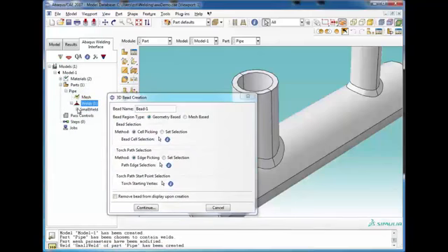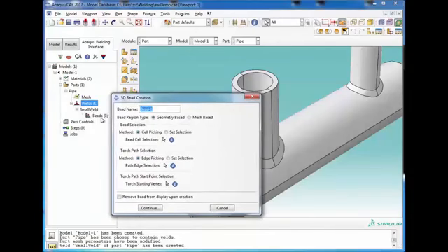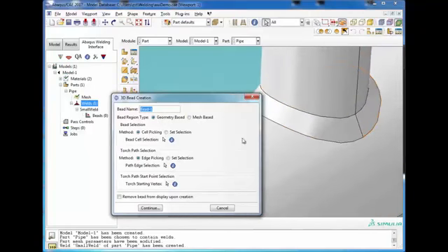popped up automatically. Now if you see the welds, this weld repository, now we have the small weld, we have beads, which is displaying as 0 beads have been selected. So that's what this dialog does. So now there are two ways of defining the beads, either geometry based or mesh based. So let's say that we are working on this. Now we have these three things that have to be selected: the bead itself, and then a torch path, which is essentially a selection of nodes along which the torch will travel, and then a starting point. Now typically the torch is going to be in the middle, kind of at the top of the bead and in the middle, let's say in this upper bead.